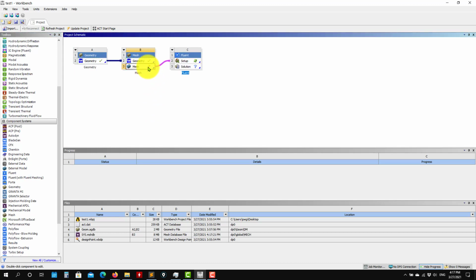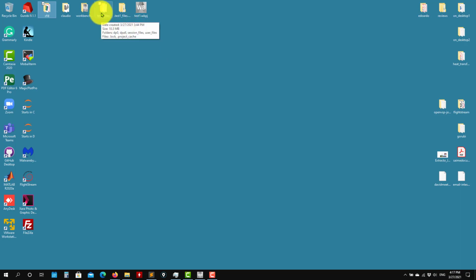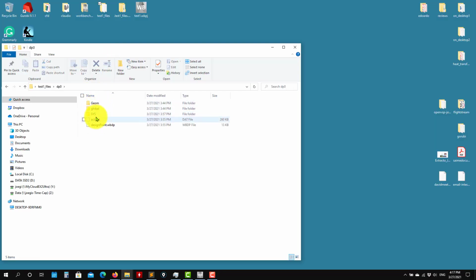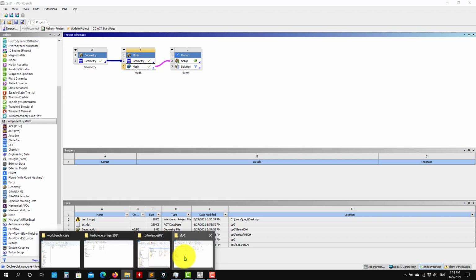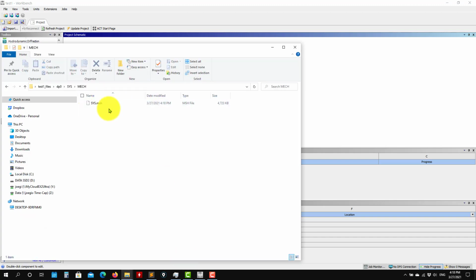and see that now you have the lightning in there, meaning that you need to update this. Right click, update. So this update is simply converting this mesh into Fluent format. See here that you have the location. So remember that wherever you put these files, in my case I'm working on the desktop, you enter here and you will see all the files. So let's wait while it's doing the mesh conversion. So see that it's converted and see here that you have the new mesh. Okay, so this is the Ansys Fluent mesh. So as you go back to that folder, see that you have it there.